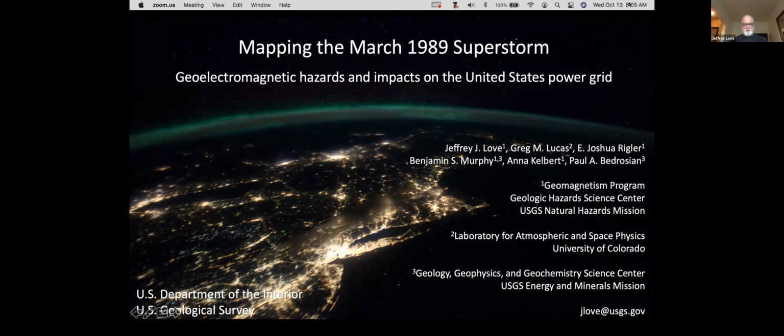There are a lot of approximations involved, and we're going to compare some of the analyses we can do with magnetic observatories and magnetotelluric impedance tensors to see about the predictions we can make regarding electric fields, and then compare that with actual impact data just to see if we're on the right track. The analysis is, I think, fairly robust, even though there are actually a lot of problems with the magnetometer data for this storm. That's not really a problem for the MT tensors.